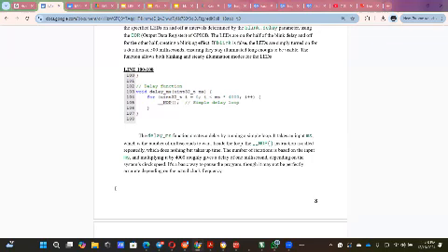Okay, so the last part is line 100 to 108. This is the delay function. What is the function of the delay function? It creates a delay by running a simple loop, which takes an input in milliseconds, the number of milliseconds to wait. Inside the loop, the NOP instruction is called repeatedly, which does nothing but takes up time.